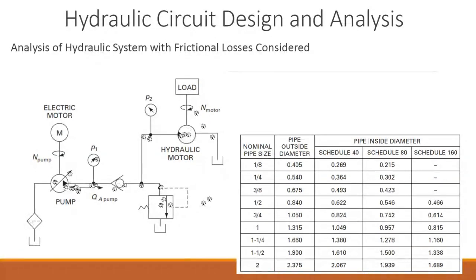And this is your pressure relief valve. As soon as the pressure is high because of some restriction or some blockage, it will just open and drain the oil in such a way that the pressure is maintained inside the whole circuit. It will not shoot up. Now, what is this?